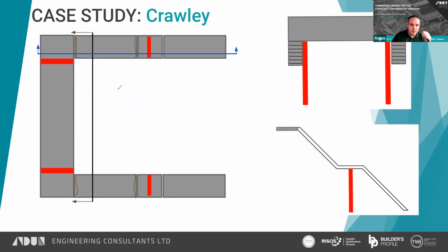Now someone had put together a scheme where they were effectively insisting that we had to put some beams on here and here to pick up the cantilever section of the bridge. By a lot of messing around and discussion with our client and indeed their client, we persuaded them that that was not the case and we could do away with quite a lot of temporary works that really wasn't required